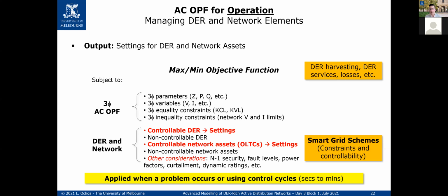Yeah, you can say that the active control of DR will be embedded in DERMS as a platform, because at the end of the day, you have your SCADA, you have your distribution management system, you have your DER management system, and these are just little blocks in a full platform of control and management of your distribution network. But yes, active control can refer to DERMS.